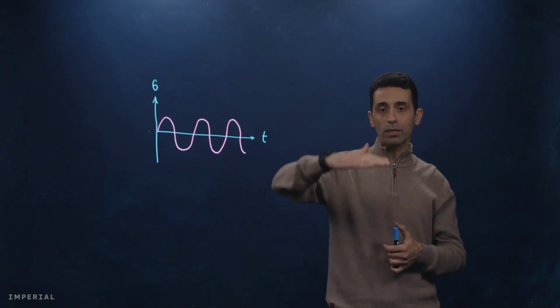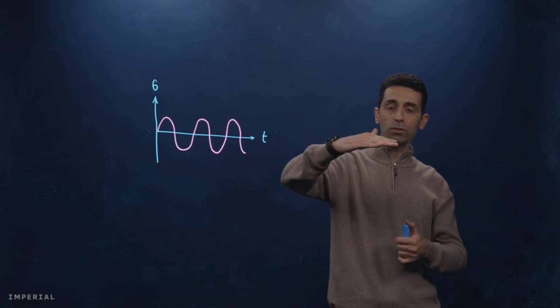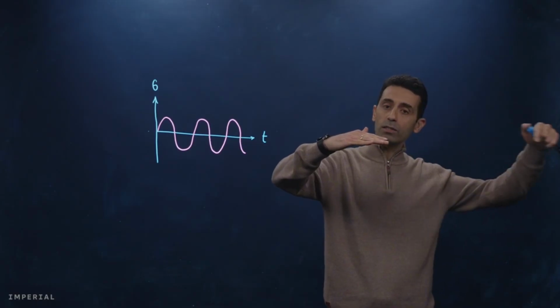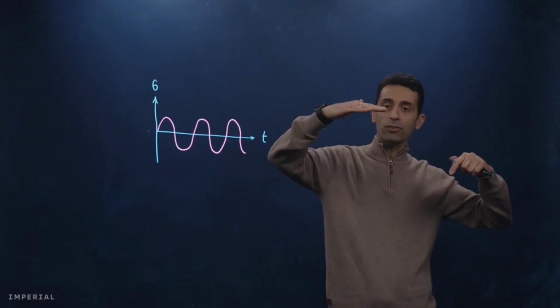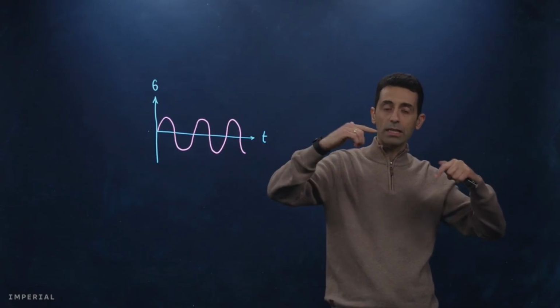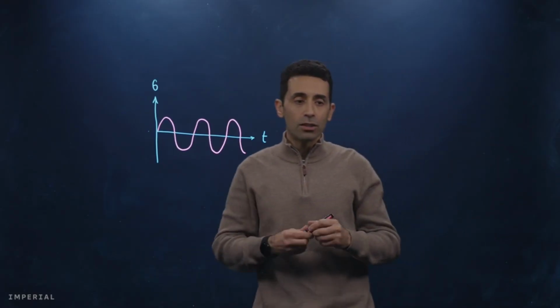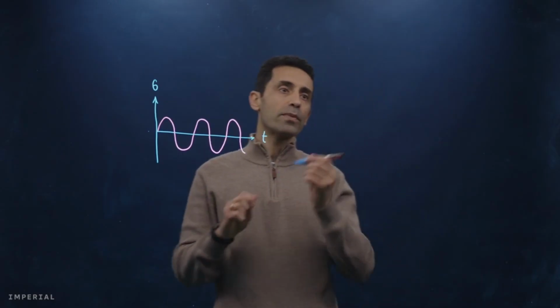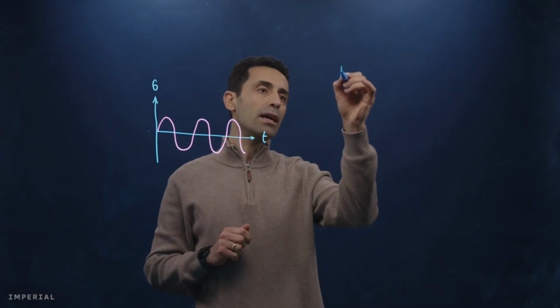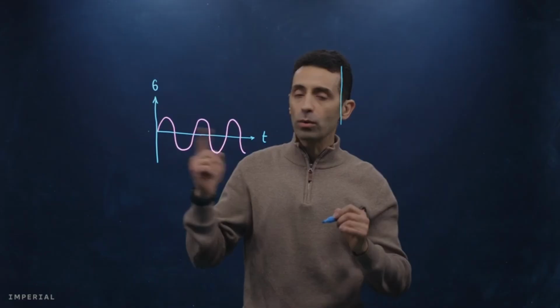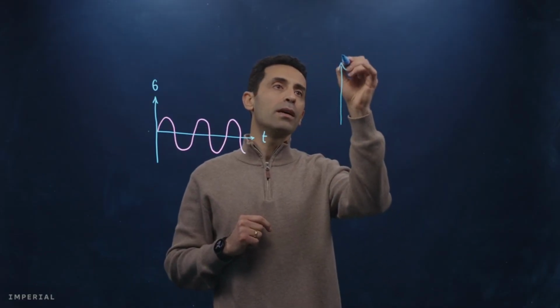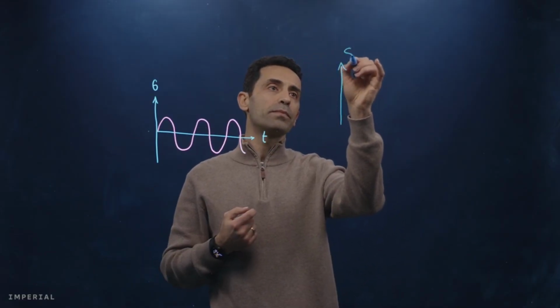We keep the load at a certain level, at a certain threshold, and we apply the load until it breaks, and then we change the load, either increase or decrease it, and again we do that, and so on. And then we can draw another diagram which has this load that I mentioned. We call it S.